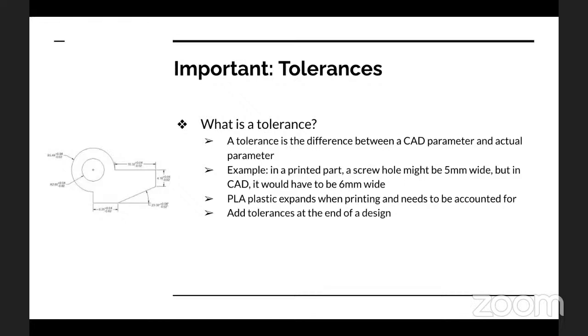So you want to designate some leeway space, so that your screw definitely fits inside the hole, even if the plastic expands. So this is just called a tolerance. And you want to use the same tolerances all around. That's just kind of easy. Once you measure it once, you don't really need to do it again, because you know how much you need to designate for a certain type of plastic.